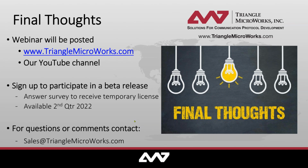So if you wanted to use the gateway testing tool that we were showing off today, you could obviously have a custom action for that. And honestly, you could probably do a mixture of the two. If you really want to see how your gateway performs under stress, you could set up some auto data changes and set that up to run periodically, kind of like the commands I was showing you earlier. So maybe every 2 or 3 seconds, 10,000 points are changing, and then you could specifically monitor one point using the gateway testing tool and verify that that value did get through.